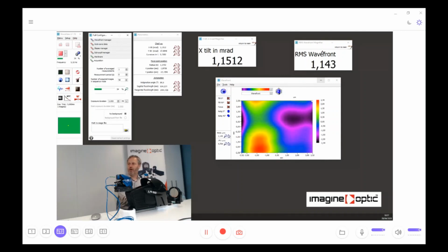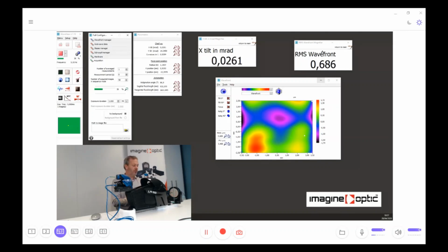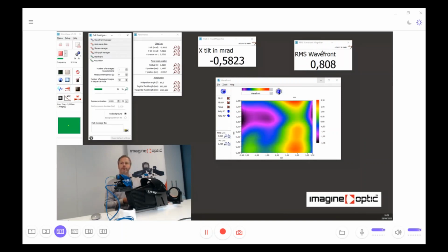And it's very easy now to characterize it, see if the wavefront that is acquired is okay compared to the specification of this glass, and analyze things. Don't forget that by knowing the wavefront, it's very easy to calculate the local curvature of the wavefront and calculate the diopters, which is closer to all the rules and normalization of this kind of device, windshield and glass. Okay.